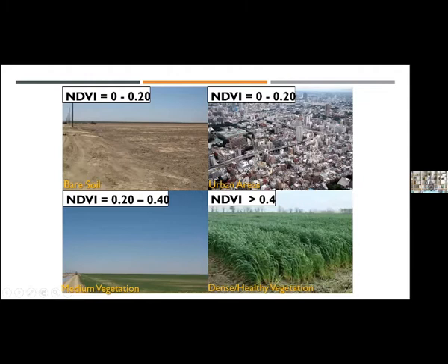And we will see in pictures just to give you more idea about this NDVI, because NDVI is a really important or a key parameter to monitor crop health. Okay, so if I have to give you just a range, point 0 to point 2, it's almost bare, and then again, urban areas is also up to point 2 or even point 3.